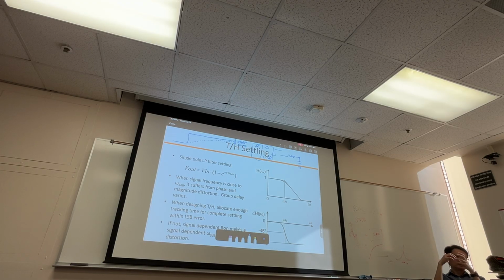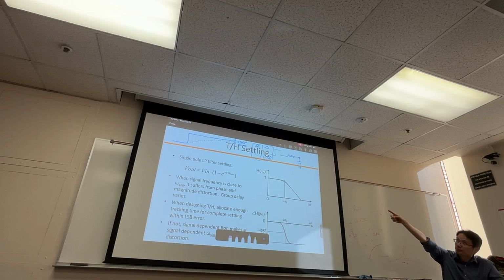You remember the SNR? You have a signal power, you have a noise power, right? The SQNR is that you look at the conventional noise power. Imagine if the error that you're making is relatively smaller than that 1 delta. That most likely means that if you compute the power here, it will be much less than your conventional noise power. Does that make sense?